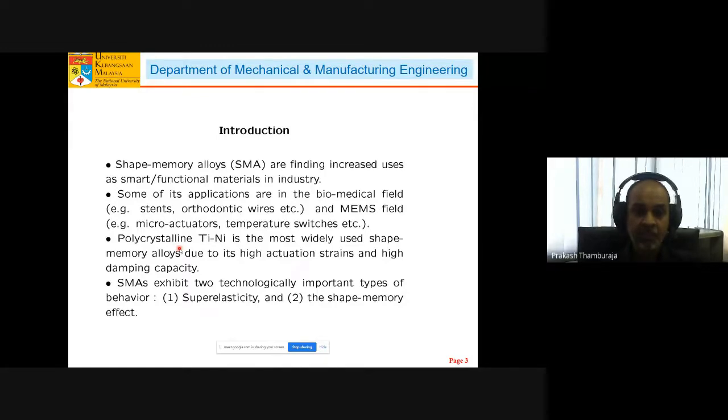So some of the drawbacks include the amount of time it takes to perform actuation by temperature stimuli. That is why a lot of shape memory alloys are made in wire form, so that the temperature actuation is faster. In fact, a lot of people also use piezoelectric materials for actuation purposes, but unfortunately, piezoelectric actuators have very small strains compared to shape memory alloys. In SMAs, the actuation strains are about an order of magnitude larger than in piezoelectric materials.